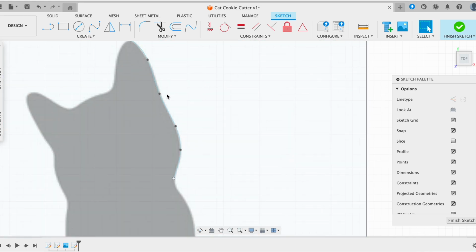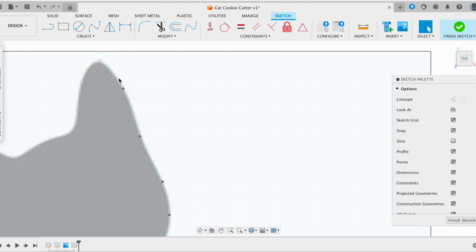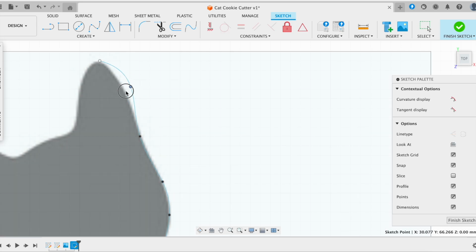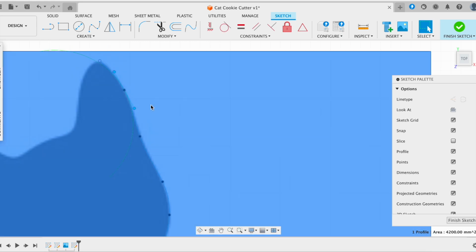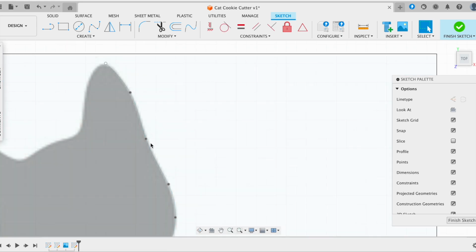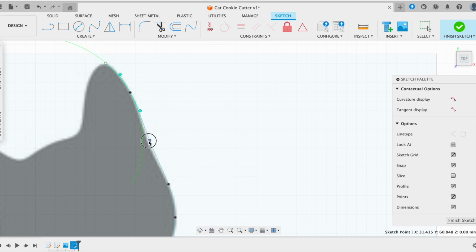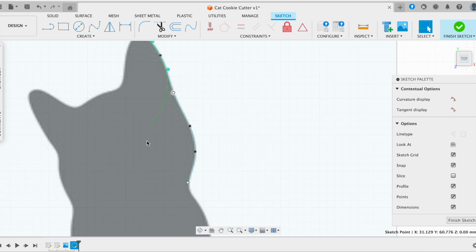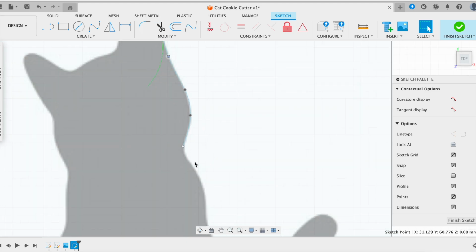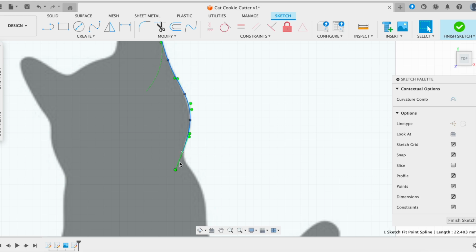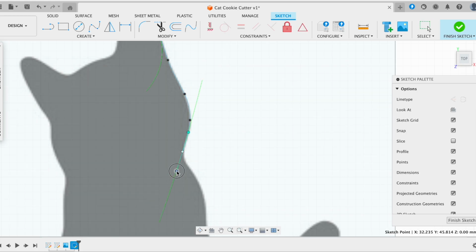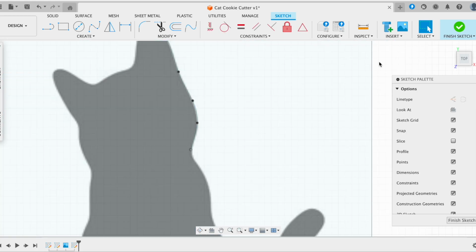And now looking at this spline line, you'll notice that there are black dots, which you can still move, and when you click them once, you can also change the angle a little bit. So we'll be using this to copy the shape of the cat. You can always edit it, and what you basically want to do is replicate the silhouette of the cat or whatever image you have as best you can, and keep changing the angles in order to make it more accurate.